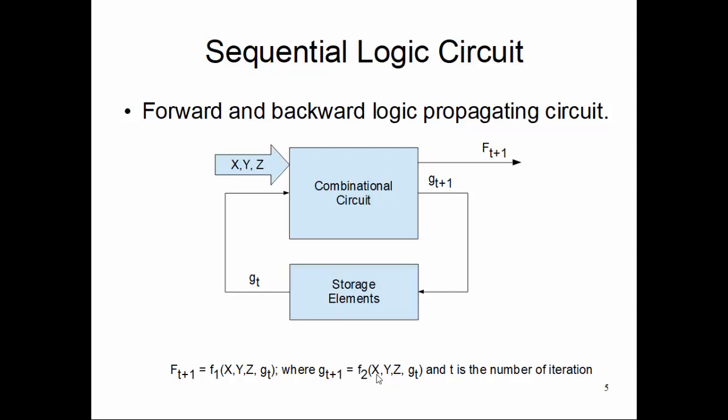What is my g0? What can be the value of some step which I never did, right? This is the first time f1 I'm computing something. G1 is also coming up on that, but I need to have something like a g0. That thing is called an initial condition in a sequential logic circuit. Every sequential circuit has a power up state.